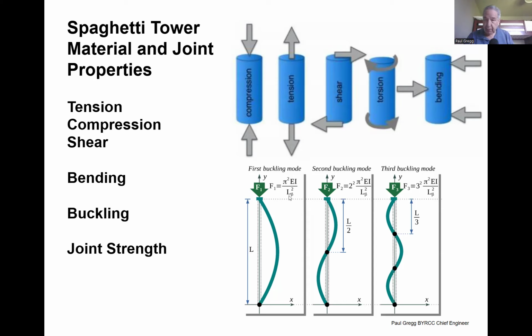But the one variable here that you can change is the length. And that is an important variable because it's the reciprocal of length squared. The buckling load is a product of these numbers, which typically don't change for a given design. This is the number that can change. So what it says is when the length is half, if you support it halfway, then the length is half, which means the buckling load has gone up by half squared, or by 4 times.